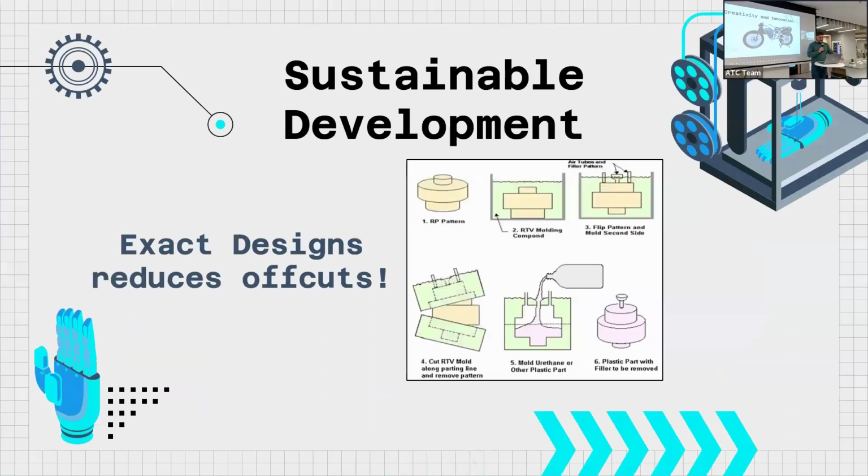Lastly, 3D printing has the potential to reduce waste and environmental impact compared to traditional manufacturing methods. As mentioned previously, 3D printing allows for super optimized designs, which will minimize material usage and energy consumption. Imagine in a factory such as this, where you're producing this part, if you want to cast it, you need to include a chute and a breathing tube, and obviously that's just going to be cut off the part, which is excess. 3D printing allows you to print the part exactly as you specified.